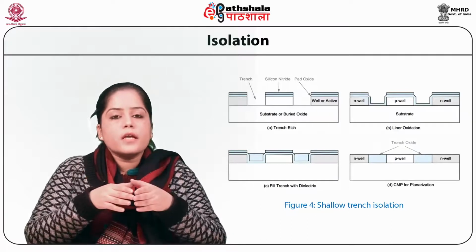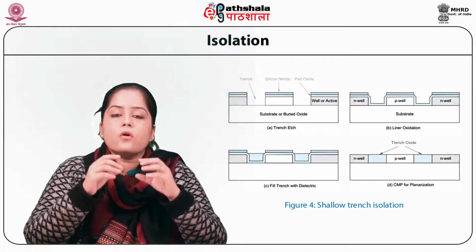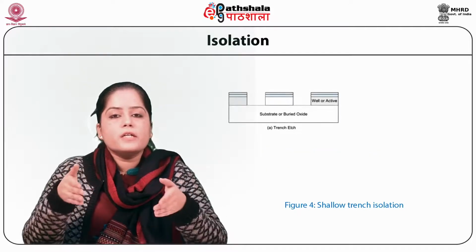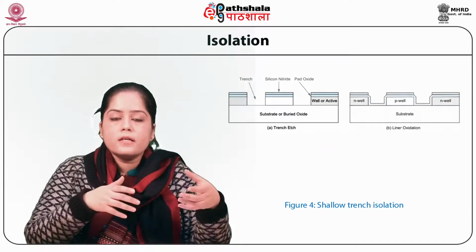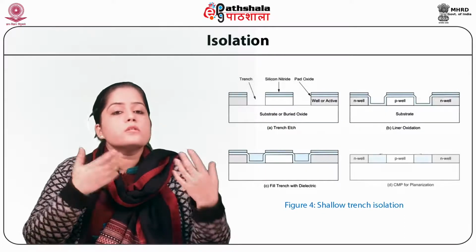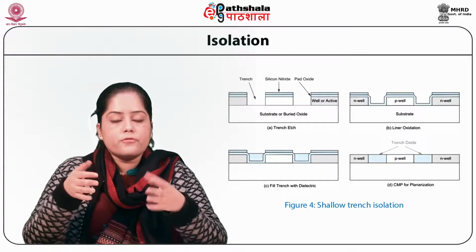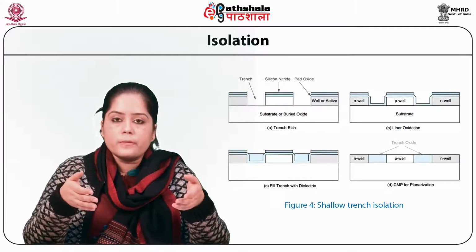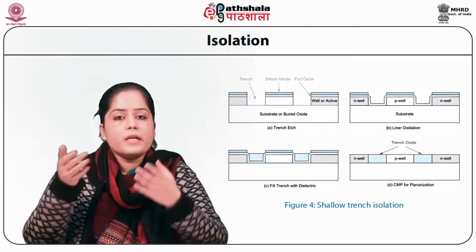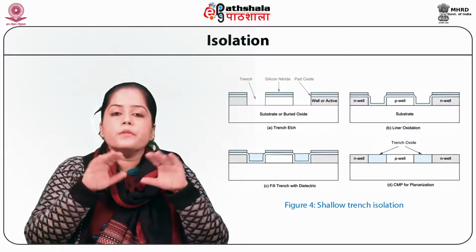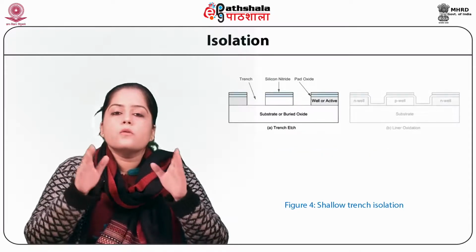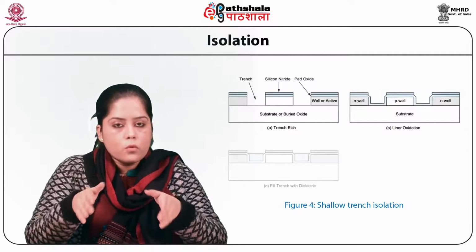The transistor gate consists of a thin gate oxide layer. Elsewhere, a thicker layer of field oxide separates polysilicon and metal wires from the substrate. So the source and the drain of the transistor, forming reverse biased PN junctions with the substrate, are well isolated from their neighbors. The thick oxide is formed by a process called local oxidation of silicon, LOCOS.